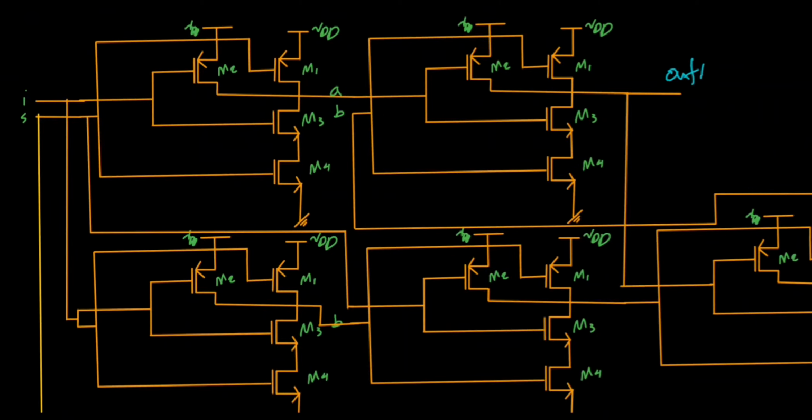In this lecture, we are going to create an 8-bit register. So far, we know how to use this circuit, and we said this circuit acts as a 1-bit memory or a 1-bit register. If the S bit is 0, the output holds on to its previous value. If the S bit is 1, then whatever is at I would be written on the out 1. So we call it a 1-bit memory.